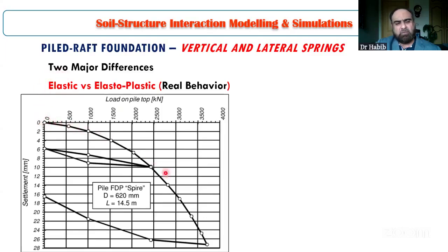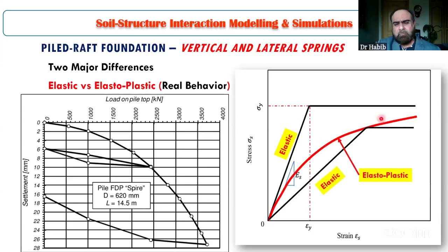We can see this is one of the load test results on the piles, and you can see that it's all elastoplastic behavior. It's not an elastic or linear behavior over here. So with this reality, again, we'll have a problem.